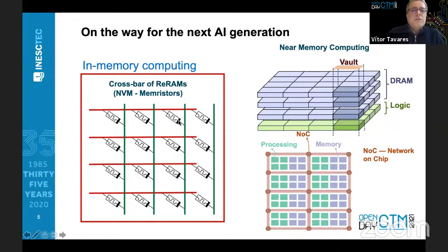Anyway, what is very interesting about this is that you can look at this device as a resistor whose value I can program with appropriate electrical settings. After I remove those excitations, the final resistor value, the state of the device, will be kept, and whenever I go and measure it, that value will stay there. So it's a memory. But you can also change it continuously, so it can be an analog memory with some processing capabilities.